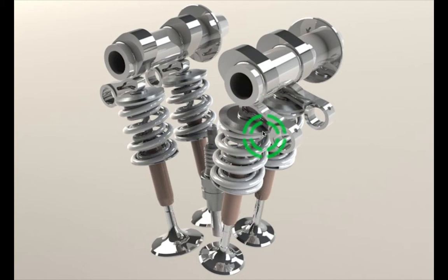So that's how it works. And the same thing applies to this. As you can see, when this goes down here, this is going to go here, because both are going counterclockwise, I think. When this reaches down, this is going to reach like halfway, because let's assume this is the intake valve and this is the exhaust valve. Obviously the intake and exhaust valve never open simultaneously. There's some overlap, but don't worry about it now. For now, it never opens simultaneously.